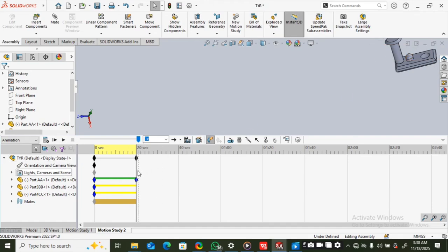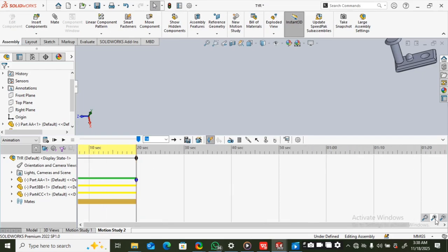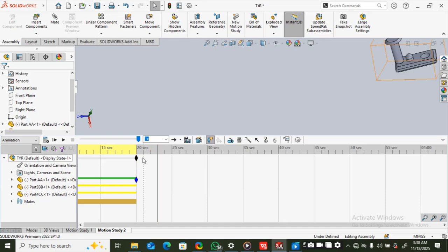So let's assume that I want this thing to come down here, like go back there, very fast. The thing you're going to do is drag this time bar. We're in 20 seconds right now, so let me zoom in to see the seconds that are given to us. Now consider this particular section, which is 20 seconds. We can count from here: this is 21, 22 and 23. So I'm going to take it to 23 seconds. So in the next 23 seconds this model is going to return back to anywhere close to the initial position,